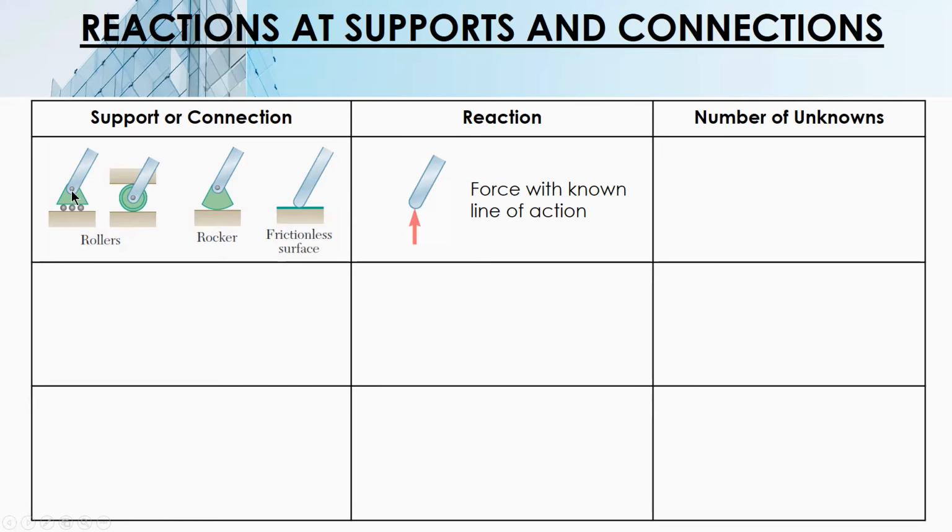if you pull it upward, it cannot resist. Right? It cannot resist. So, it's not possible that its reaction is downward. If you pull it upward, it's free to be pulled upward, right? No resistance. So it's impossible that the reaction is directed downward. But if you push it downward, the surface will resist, a reaction, this one. Okay.